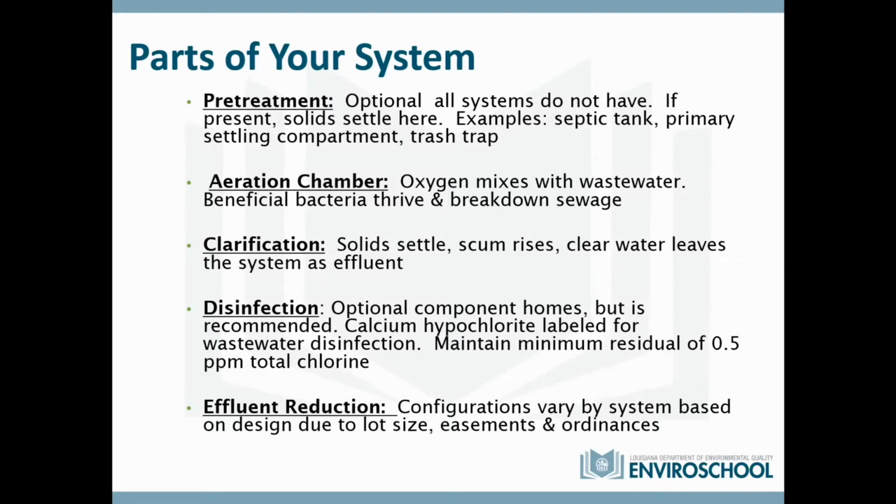What they do is they use calcium hypochlorite. It's actually labeled specifically for wastewater disinfection. This is the most common thing we see in Louisiana. It can't be like a chlorine tablet for a swimming pool. It's got to be a specific type of chlorine tablet that is specifically for wastewater treatment. And the Department of Health says you have to maintain a minimum residual chlorine of 0.5 parts per million. So that is actually in the code.